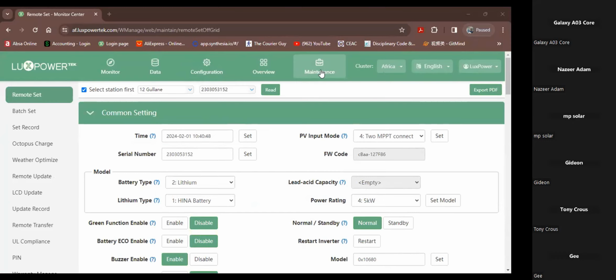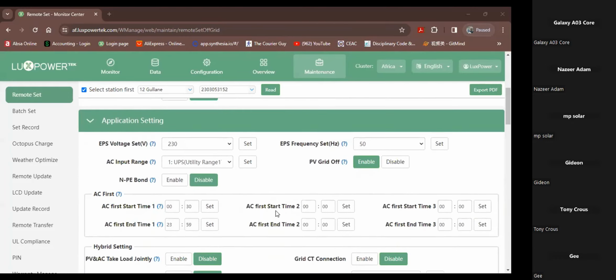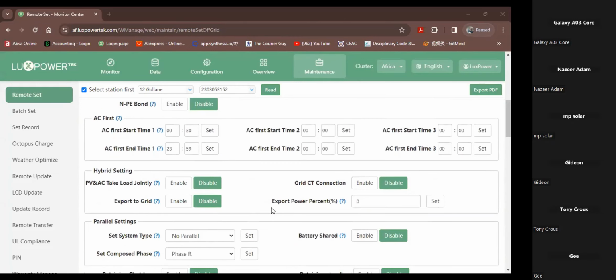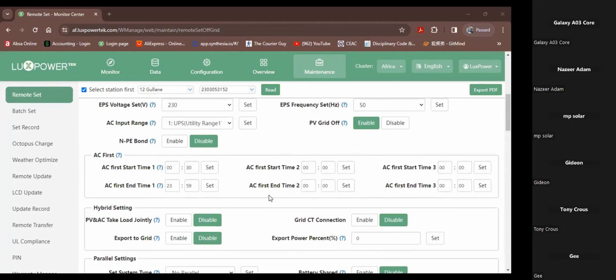daylight saving. All right, so Rian, inverter gives feedback even in off-grid mode. We've measured max 14 volts AC, normally between 3 and 5. Some prepaid meters trip because of that. Can I set a buffer on the inverter to let the prepaid pass through a certain amount of watts to not see feedback? Yes, you can. So the first thing you're going to do, obviously, is make sure that you have your bonding correctly, which is what we've discussed. And then the other thing is you're going to go down here and you're going to set your, I just need to move this chat out of the way.